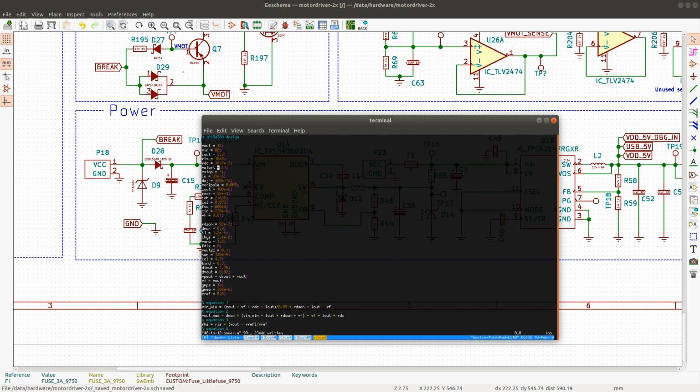The next thing is, when the input voltage rises, this parameter specifies the voltage at which the regulator will power on. It has to be higher than the output voltage, and it has to be higher than the minimum input voltage, which is calculated using the equations here. So I chose 17 volts.